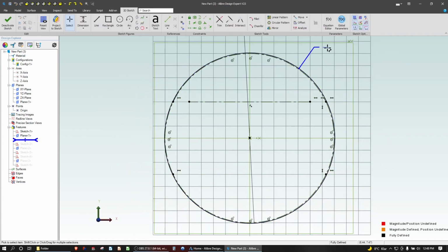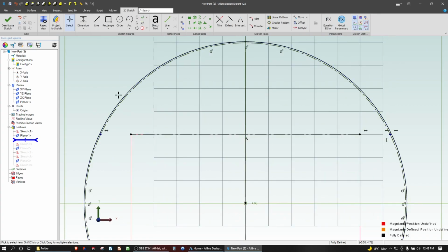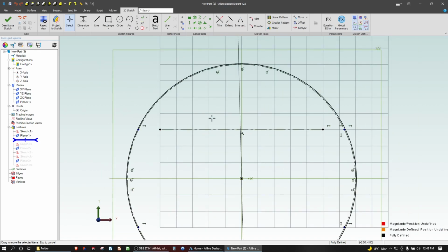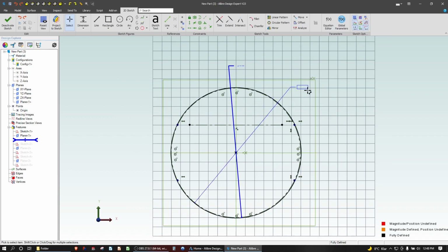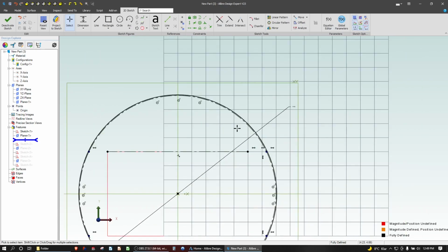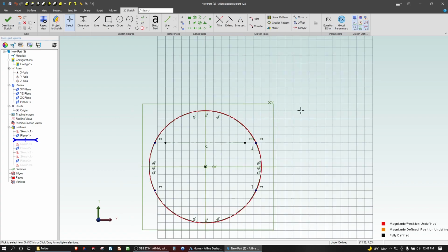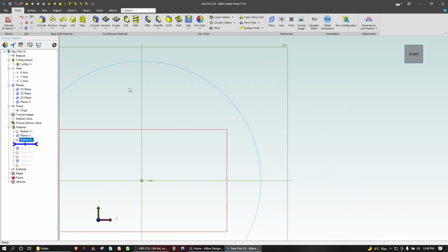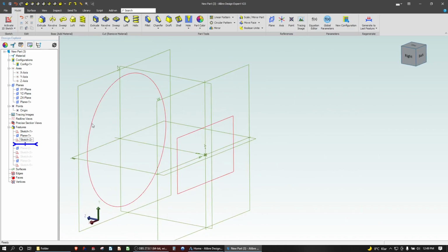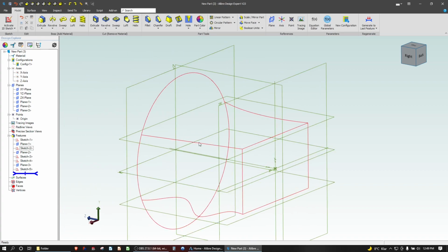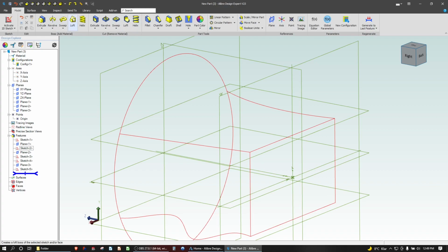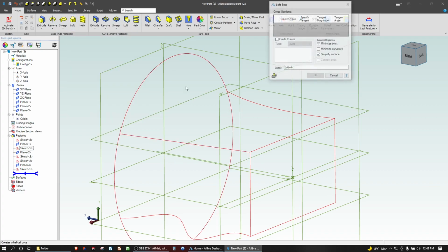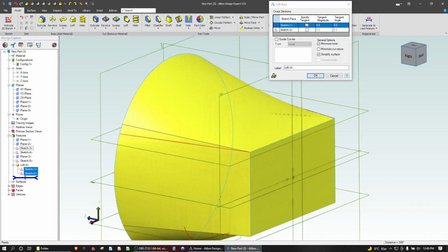Sketch 2. I'll delete this. Here's our diameter of 14.1. If I get rid of that, and then we'll say our circle is equal to our construction line, we'll deactivate that. So now with the circle being the same size as the construction lines, I can move my history tree. In fact, I'll just generate the last feature. Now can I go to a circle that does intersect those guide curves, but we're not intersecting a vertex on the circle. We'll loft from here to here. We'll add a guide curve there, and it does work.